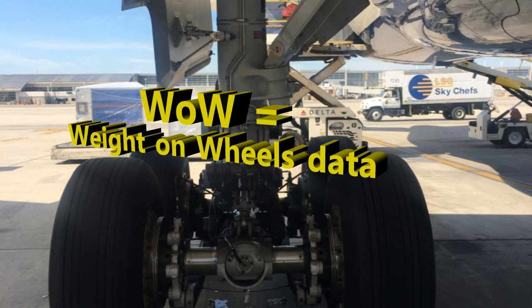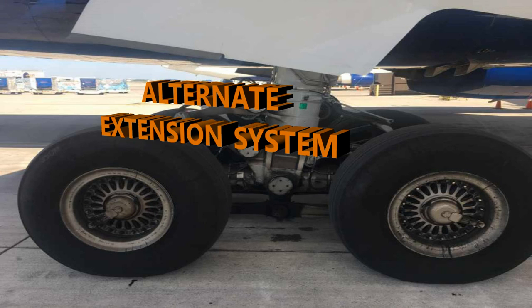Okay, all right, so that's the weight on wheels data. You also have an alternate, because you have normal operation of your extension and retraction, but let's say something gets hung up for different reasons, and there needs to be an input from the pilot to go to an alternate operation. There is a module in the cockpit.